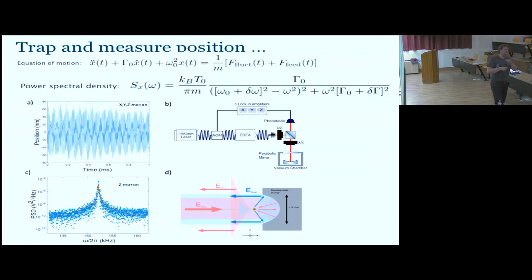These guys do it on the order of tens to hundreds of nanometers. The trick is that they have an optical interferometer, which detects the position of the milling tool with respect to the piece they want to work on. They claim that the surface roughness of this mirror is only determined by the material itself, by the grain size of the aluminum.